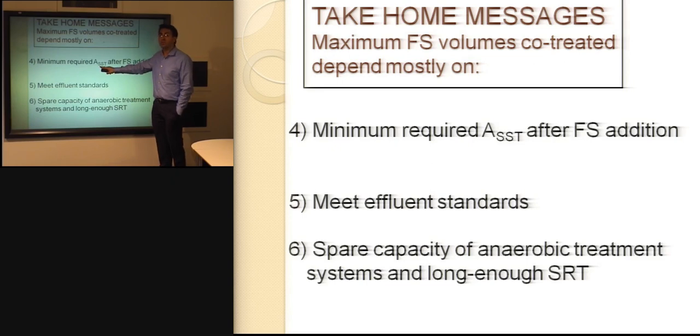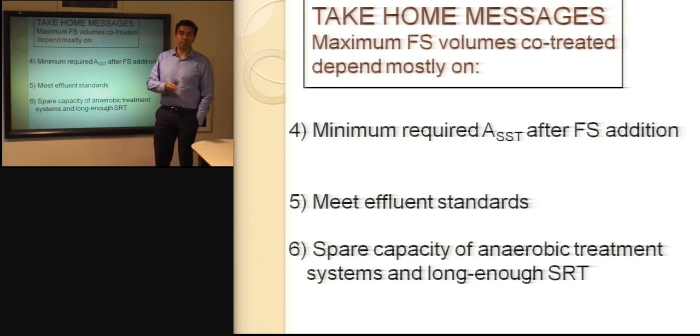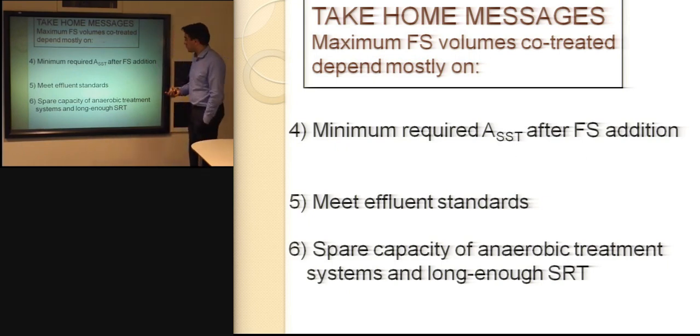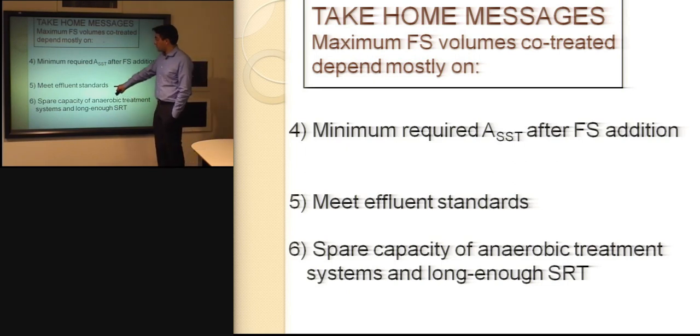What also needs to be foreseen by a designer, and in most cases this is not a common practice, is that the effluent standards will likely be exceeded, because the concentrations of unbiodegradable soluble components, either organic or of nitrogen origin, will be much higher, and because they cannot be removed, they will have the strongest impact on the effluent standards.